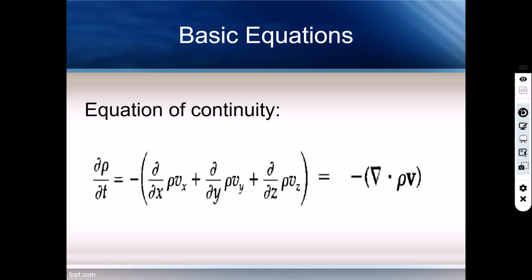And that's why the partial derivative of rho being zero is not a sufficient condition for incompressible fluid. Because the partial derivative equal to 0 means this whole thing equal to 0, and it does not lead to this thing equal to 0. You still have this one, right? Still have this one. All right. And now let's take a look at this one and that partial derivative and try to get this one.